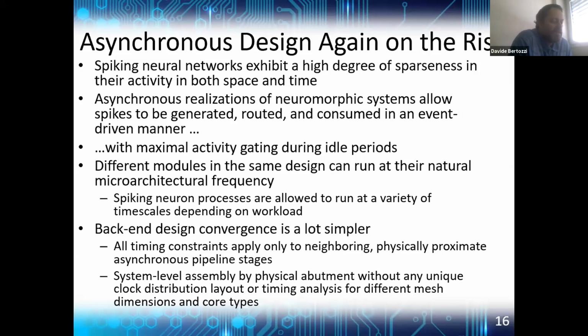Another advantage of asynchronous design is that each module in the design can converge to its differentiated local operating speed. In other words, there is no need for performance equalization, both within individual pipelines and across different pipelines in the design. Every pipeline stage can naturally operate at its natural operating speed, and the coordination with each other takes place through clockless handshaking.